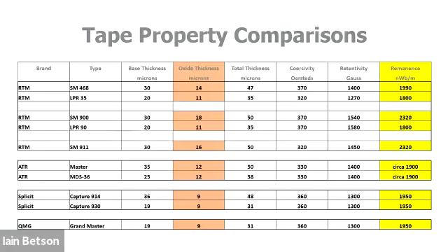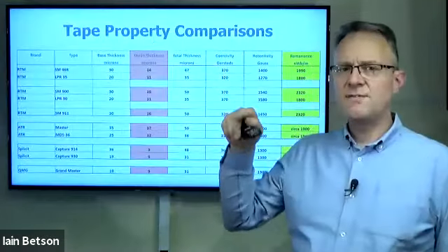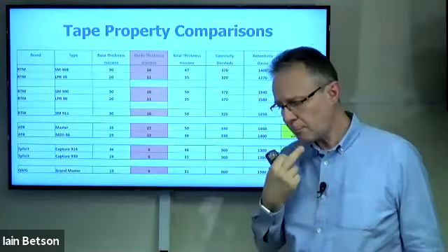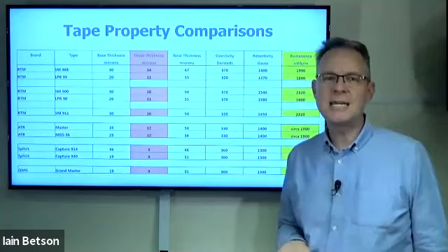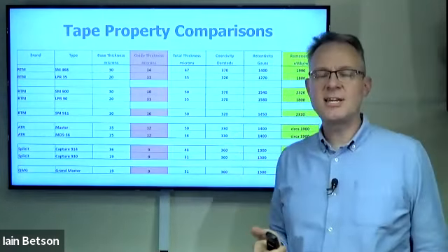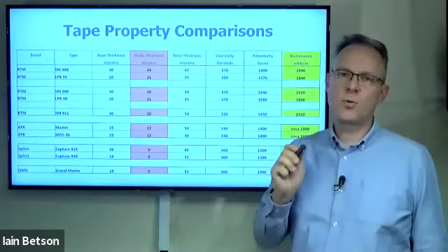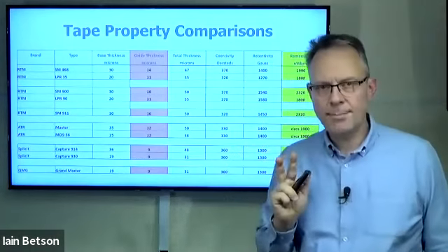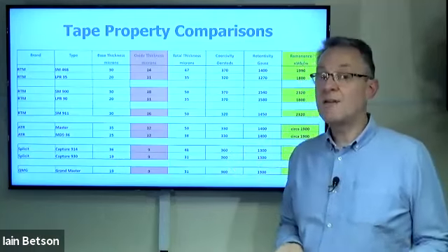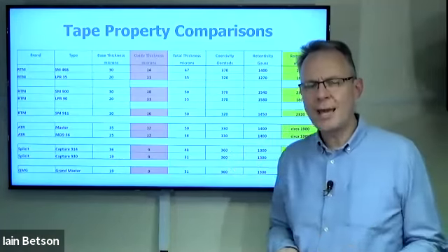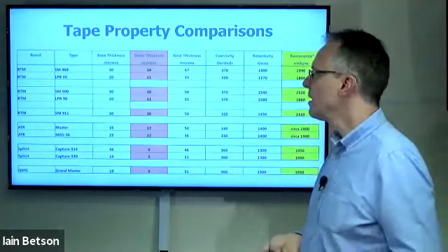As a small aside, if you're seeing tapes that have got 35/90 on them, and a lot of old tapes have that, I saw some TDKs the other day that had 35/90, the 35 stands for the whole combined thickness of the binder, the oxide, and the backing. So therefore, it is quite a thick tape. It will be a long play tape.